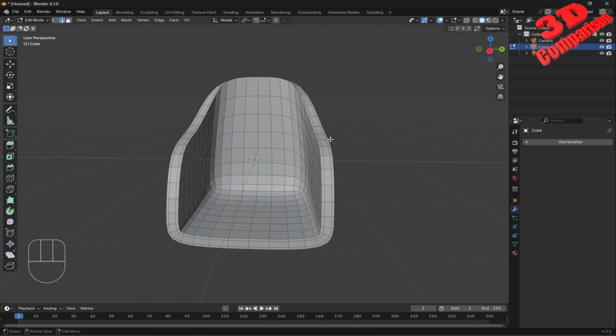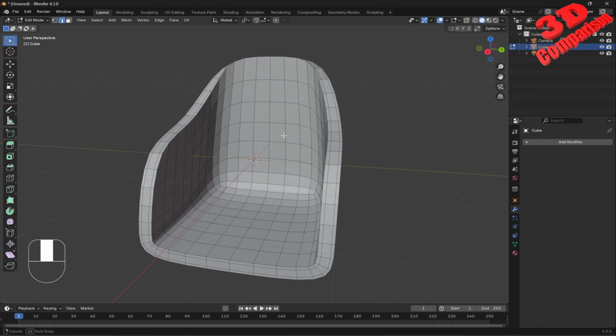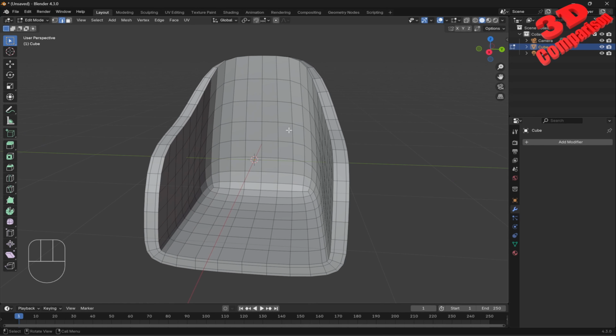Now we're going to use a tool that is within sculpting, which is named cloth filter, and we can also specify that some areas will not be influenced. So let's take a look at the following. I'm going to do a multiple selection, and this will require the use of Ctrl and Shift. So for example, with edge selection, I'm going to select this edge, and if I hold down Ctrl and select the one on the other side, Blender will give me the following loop over here.